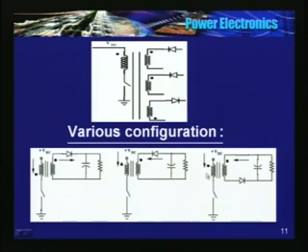So similarly here, current enters the dot. See the diode connections now, I have interchanged. I have connected a diode here. Now this is positive, this is positive, this is negative. Now this can be a reference point. Okay. So you can have multiple outputs. So the point to be remembered in flyback is that diode connections are very important. You should connect the diode in the secondary in such a way that only one winding is carrying current at a time.